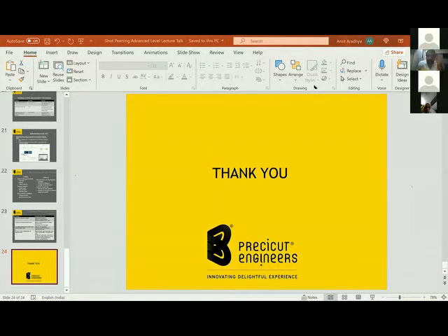The second part, which I have mentioned, is the coverage. At the saturation point you have 100% coverage, but as a design engineer you should add a safety factor here as well. If you have achieved your results at 100%, then you can definitely add a buffer and say 125% or 150% in the process. Even if there is any deviation, that extra cycle time is going to take care of the stresses, and at the same time the arc height is not going to increase because it is going to be within that 10% range. So these are the two major parameters.